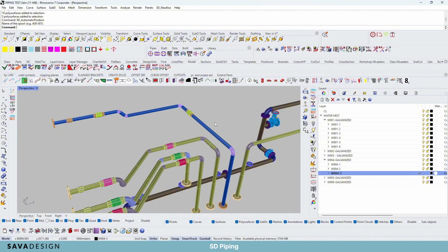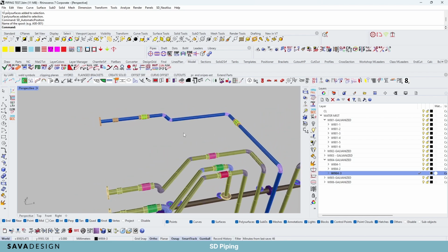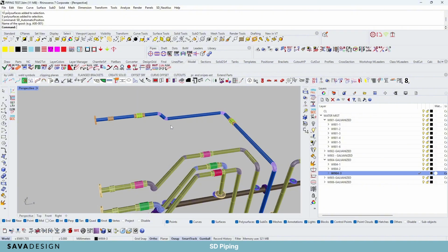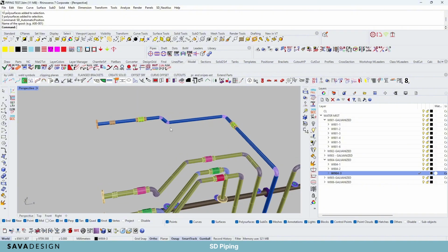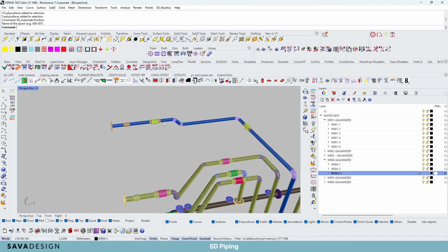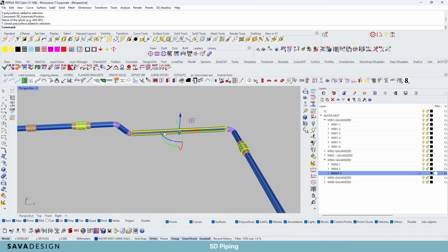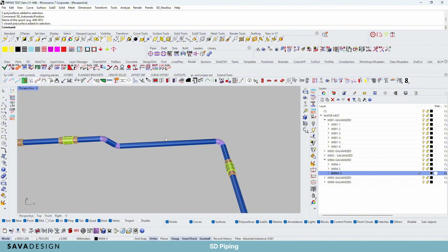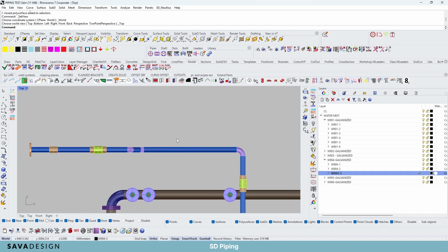So if you want to, for example, we can insert a flange. Let's take a pipe, we can run the modify pipe command. If you take the pipe, the one that is between the two double sleeves that doesn't have sleeves on it, that should be easiest to demonstrate. Okay. You can go into, for example, top view and run the modify pipe command and select the one pipe we want. Yeah, like that. That should be good enough.